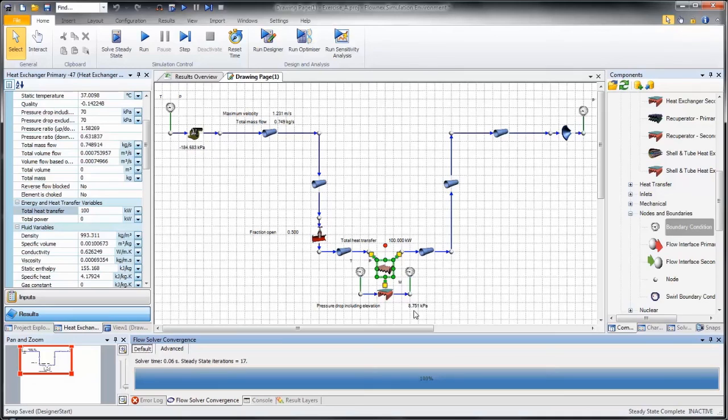Important to note is that the direction of the arrows doesn't determine the heat exchanger's flow convention, since I specify whether it performs as parallel or counterflow. So I can draw them any direction I'd like to simplify my network layout on the canvas.